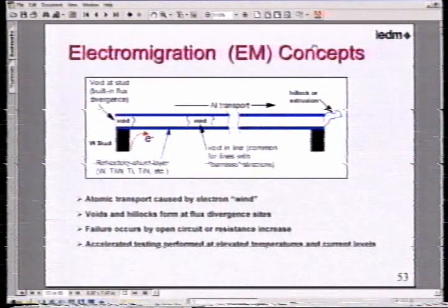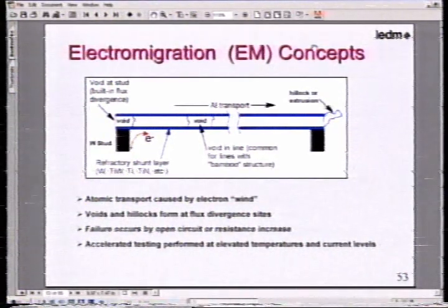Your parametrics are going to fail. And this can even happen for copper. I'm showing the aluminum part. In copper, for example, when you see these kinds of electromigration for lines which connect contacts, you even start seeing functional fails. So this concept of seeing time-varying change of resistance is a huge issue to the parametric as well as to the functional yield.